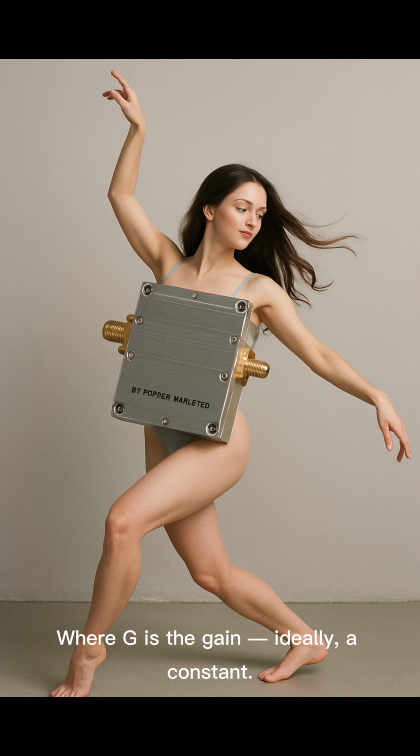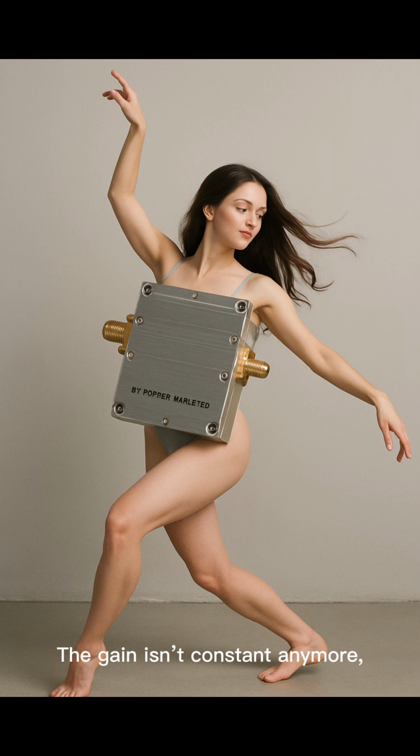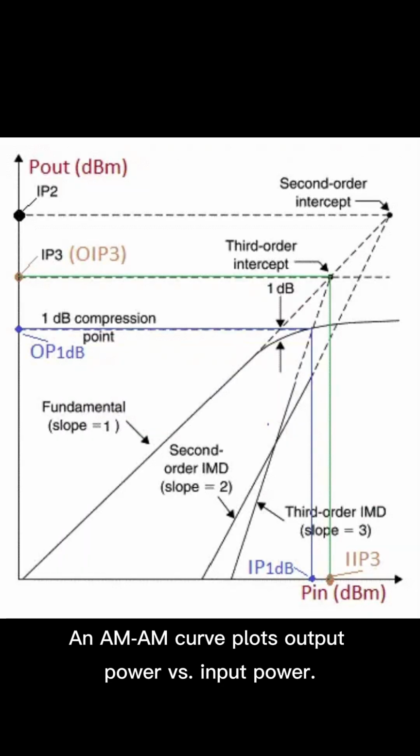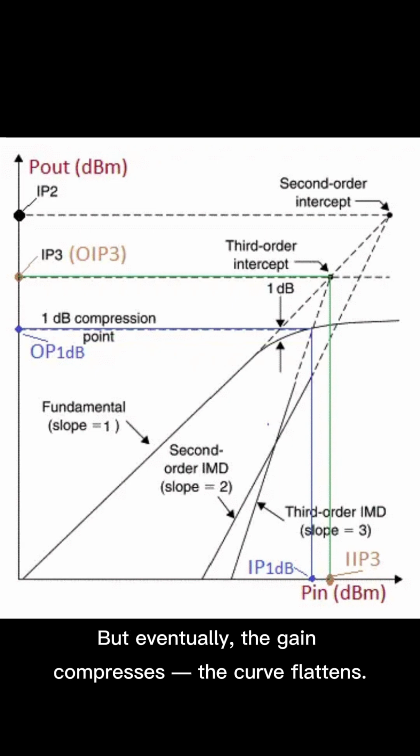ideally a constant. But in reality, as the input power increases, the amplifier starts to saturate. The gain isn't constant anymore, and the output curve begins to bend. This is where nonlinearity kicks in. An AM-AM curve plots output power versus input power. Initially, it's a straight line, the linear region. But eventually, the gain compresses, the curve flattens.